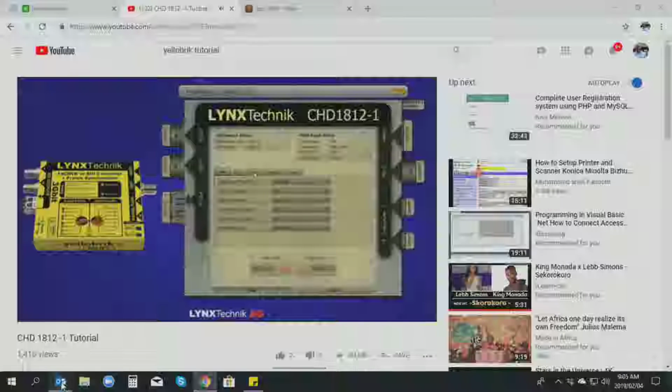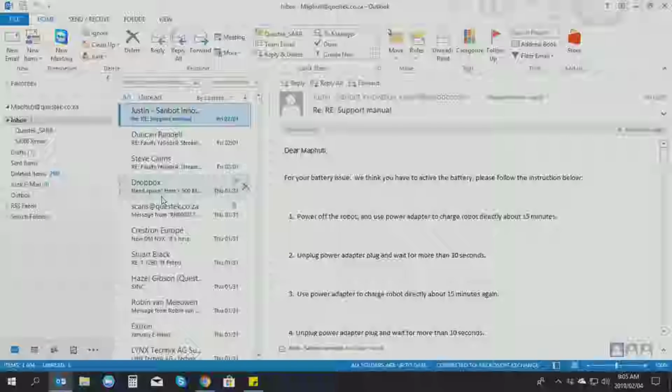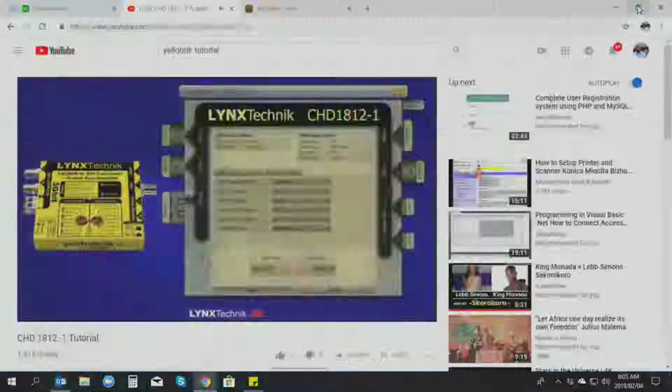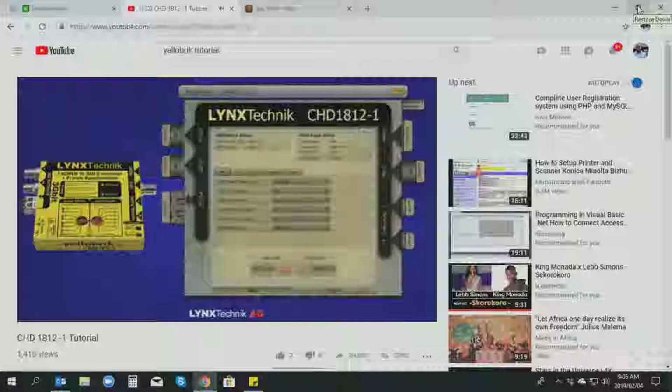So that's the module itself, pretty much self-contained. There are two SDI outputs, just a word. These are duplicate outputs, which means it's the same signal on both spigots. It's not left eye, right eye, link A, link B, or anything like that. These are just two copies of the same signal, and there's a cage provided on the module for an optional plug-in SFP, fiber SFP, which comes in various different flavors, connector types, and also CWDM versions. So you've got an optional fiber output, which can be useful.